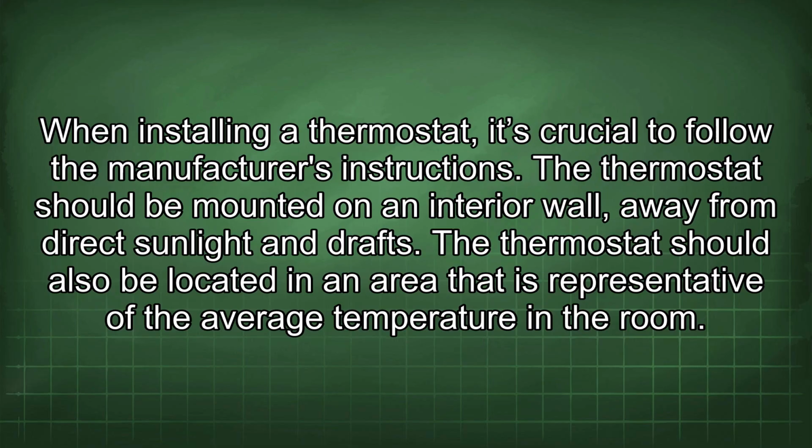When installing a thermostat, it's crucial to follow the manufacturer's instructions. The thermostat should be mounted on an interior wall away from direct sunlight and drafts. The thermostat should also be located in an area that is representative of the average temperature in the room.